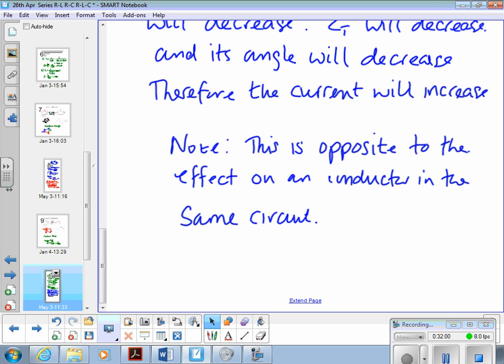Okay. To clarify that opposite action: in high power systems, so supplies to big factories, really high inductive loads, transformers, motors, welders, etc., cause the issue with current and voltage being out of phase with each other. I'm not going to explain why, but what it means is you have to supply more current overall through the cables to deliver the same amount of real power in watts to those loads.